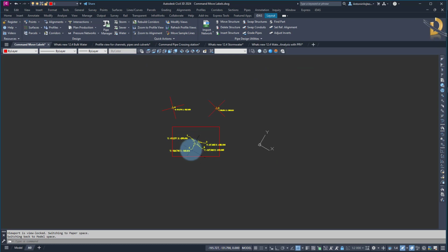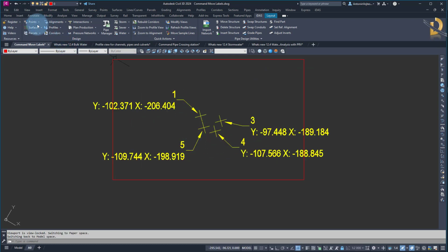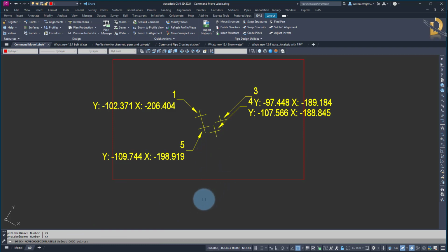And if I run that command again, let me go to rotate labels or adjust labels, overlappings, and then I go to select points. Yes, I want to use a distance 30, and I want to use a angle 45 degrees. And as you can see, both do have the correct slope. For example, this one should be probably a bit longer. I select it. As a length, I will use a 45, as an angle 45, and it looks much better.